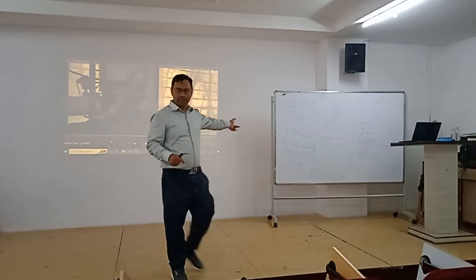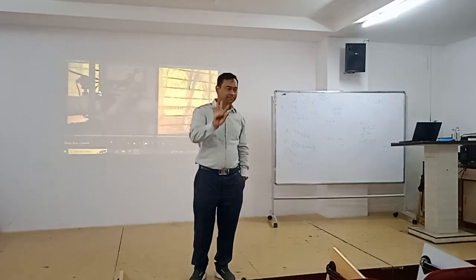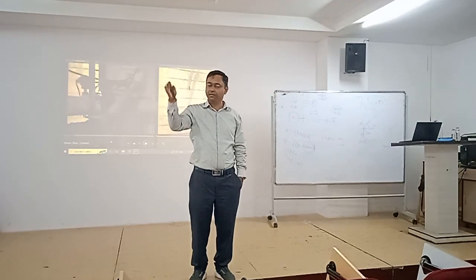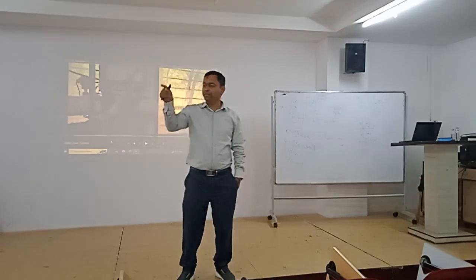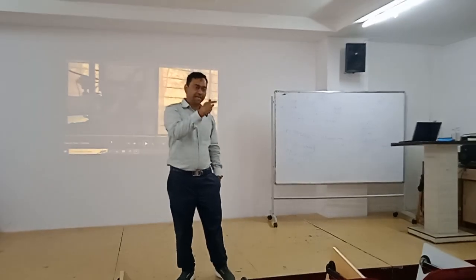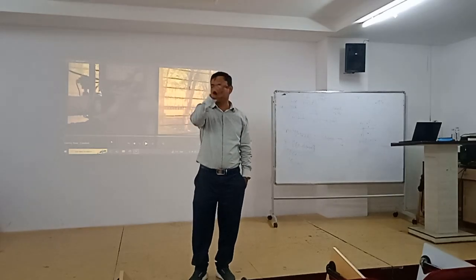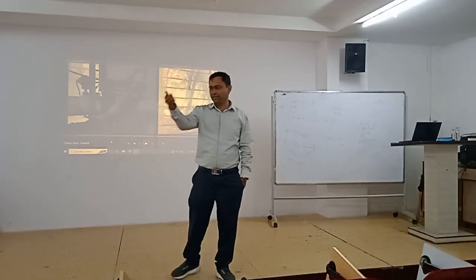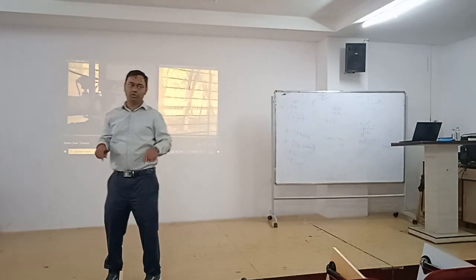So this system is working in closed loop. That's why we are getting the desired flow. Whatever flow we are setting, we set 100 earlier. Initially it was not coming, but after doing some setting, it was coming. Then we set 50, it was achieved. We set 0, it's achieved. Correct? So the desired value of flow was 50, and the system is working in closed loop. That's why that is happening. Definitely I'll discuss it a little later, once we go into much theory.